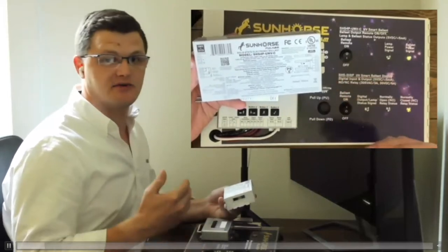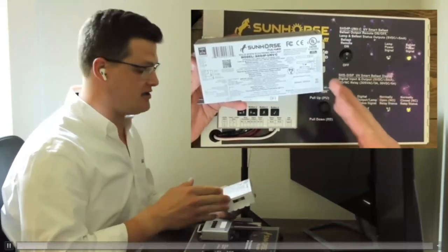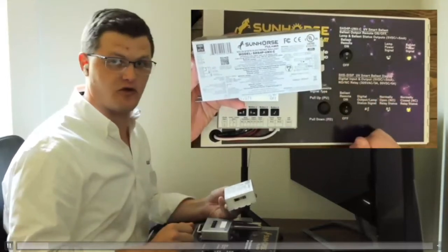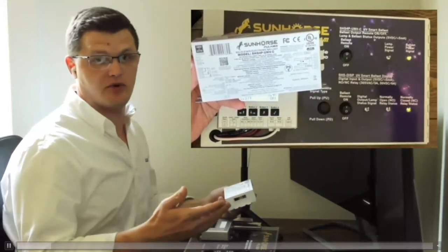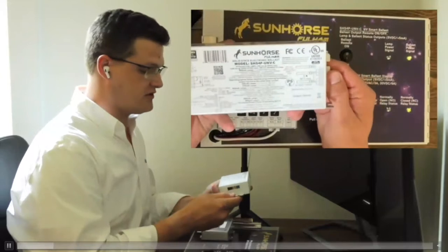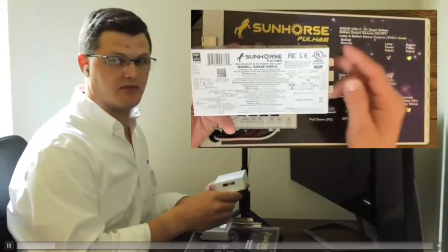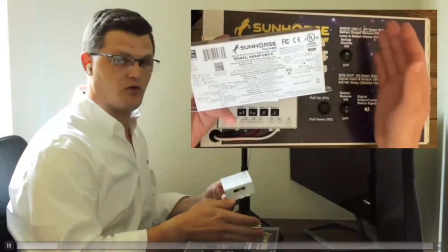We've also added some incredible new features like programmability for the ballast from 400 milliamps to 800 milliamps with this SHS-4P, or 800 milliamps to 1.2 amps with the output of the SHS-15P. This one again can handle up to 100 watts of loads in either 1 or 2 amp configurations, and the 15P can control up to 330 watts of load.